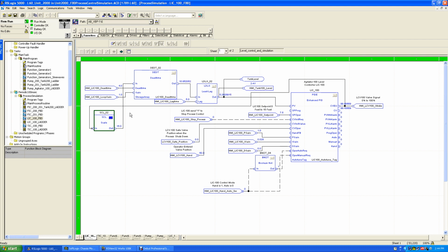That allows us to, when your process is oscillating back and forth in hunting, it can go above the 15 set point and go up to 20, and that allows the input to show you your oscillations when you're poorly tuned. Okay, then we take that 0 to 20 out, and it's going to be 15 maximum. We've set it to 15 maximum. You see it goes up to 15 maximum. It's just oscillating back and forth because it's poorly tuned right now.